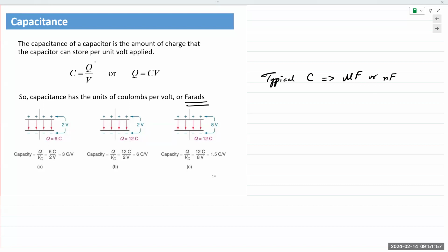In microchips, we have billions of transistors. And so even if you have a capacitance for each transistor in the femtofarads, which is 10 raised to minus 15, now you add hundreds of billions of transistors, all of those tiny capacitances add up. Those capacitances will short out your circuits in unwanted places. Okay, just a real life example.